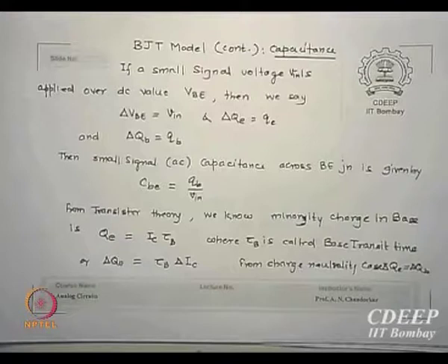Whenever I say frequency, time constants are associated. Is that correct? 1 upon RC, 2π by RC is the frequency. So whenever I say frequency, I am looking for RC terms. So now I must look at two more terms. GM of course is the transconductance. Now I must look for R as well as C because I am now looking for bandwidths. Gain I know GM will help me out, but I also want bandwidths. So I want to know how I will control that.